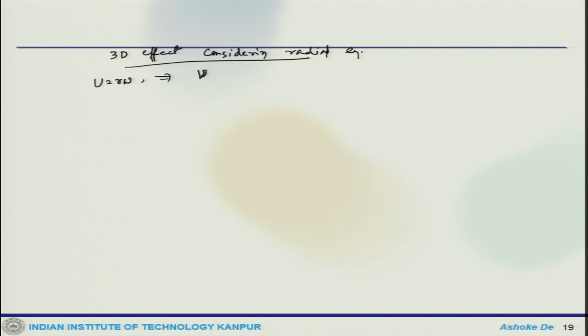So, U goes up as the rotational speed goes up as r goes up. So, to maintain a smooth flow, the blade has to be twisted. So, a twisted blade is required. Second, twisted blading is designed to take into account the changing gas angle, which is called the vortex blading.